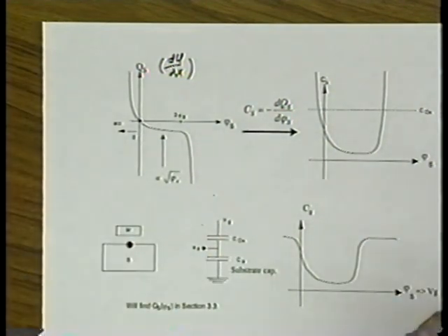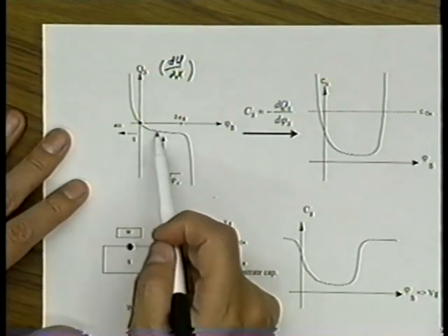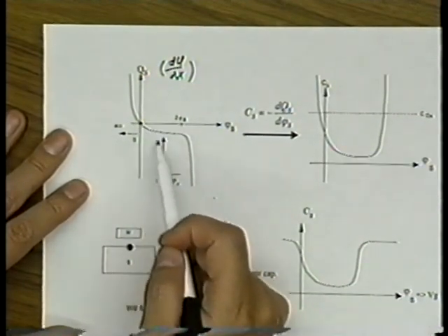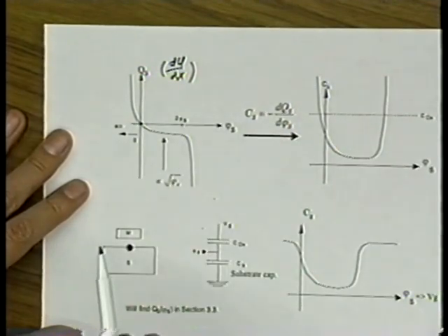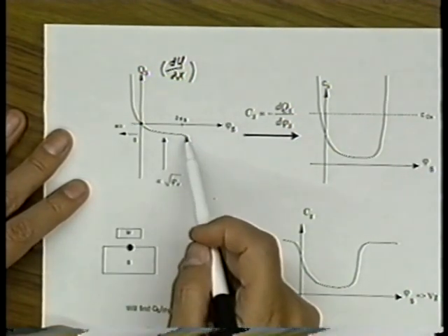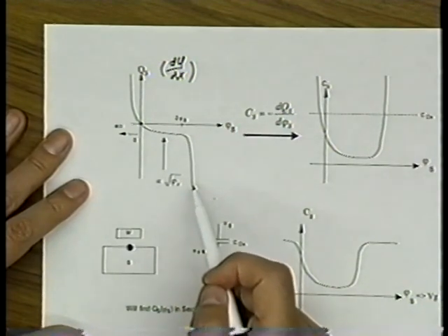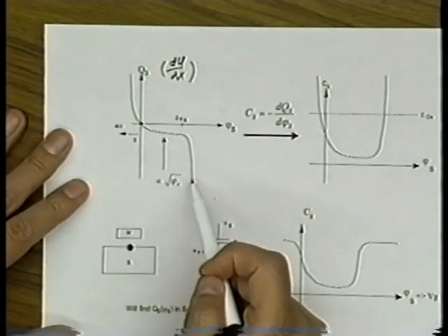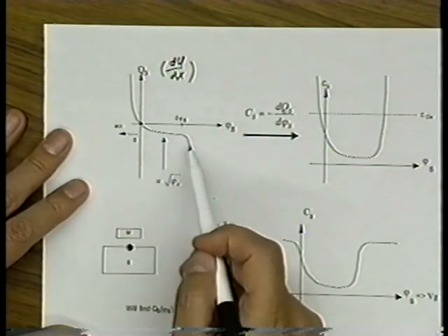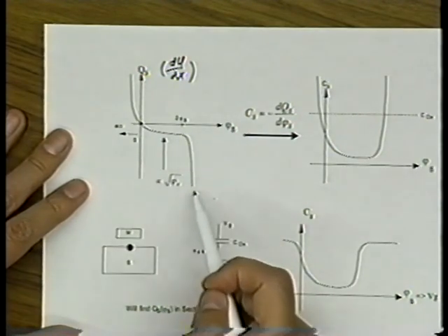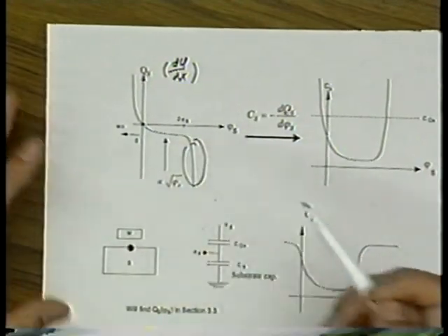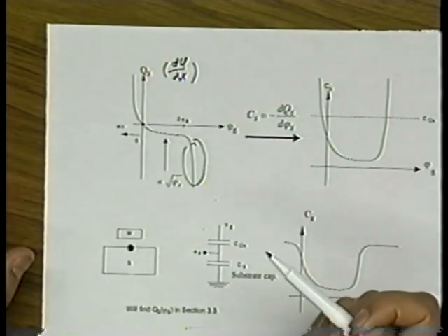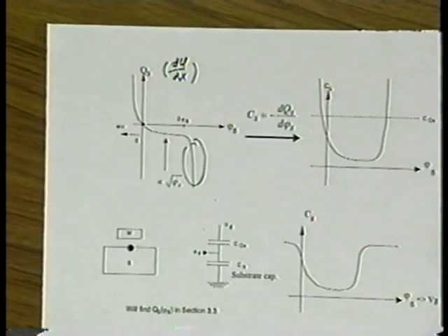That's correct. In the depletion region, this very much is just our Q depletion, very much like the first order model would tell you. Nothing wrong. Beyond the VT, the charge increases rapidly. What is this charge made of mostly in this inversion region? It's the inversion charge, right?